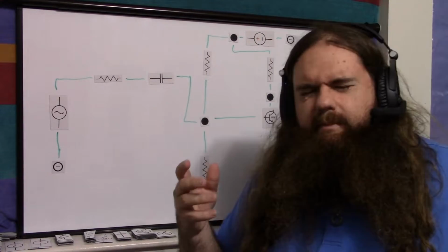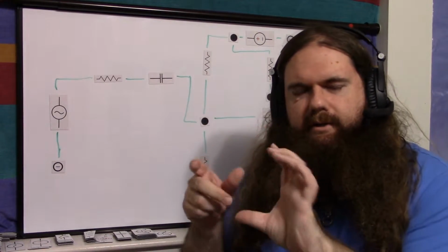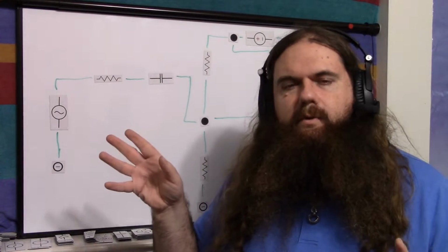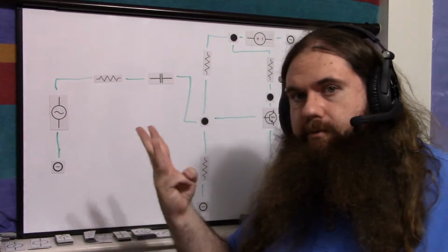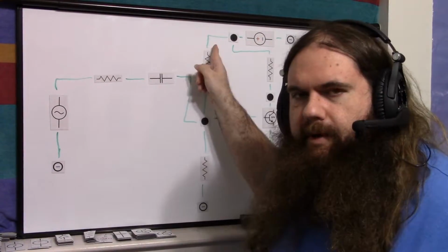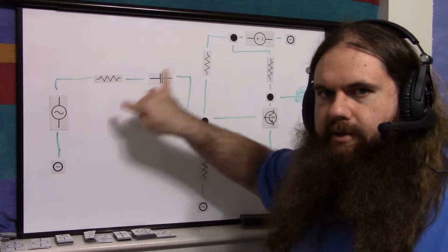I'll show you in a second. But let me just remind you of the video I did where I had 2 power supplies and you can interconnect them as long as you only interconnect them at one point. That's how this works. You have, in fact, 3 power supplies, 3 EMF sources, voltage sources: the signal, the positive power supply, and the negative power supply. In this one, you have 2. The signal and this power supply are separate.